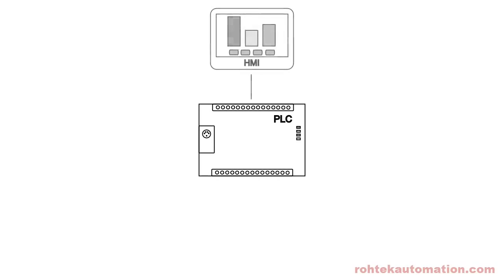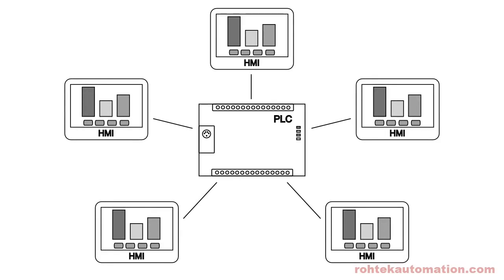The development and maintenance of a system is determined in large part by its design and its documentation. If we take kind of a haphazard approach to how we interface the HMI to the PLC, we may end up making more work for ourselves or others down the line. If we want to make even minor changes to the PLC program, which happen to affect the areas accessed by the HMI, then the HMI or HMIs will have to be reprogrammed as well.